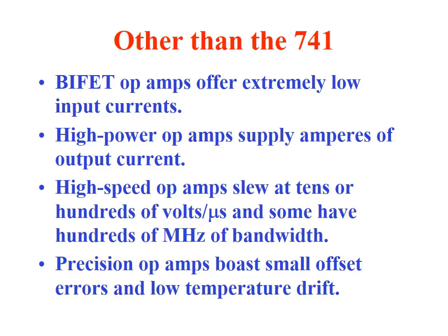And usually, as I said, for some operational amplifiers the unity frequency is 100 megahertz. The precision op amp boasts small offset error and low temperature drift. So that's a better operational amplifier. But why don't we use these operational amplifiers a lot? We mainly use the 741. The main reason is this one is very easy to use, and the second reason is the price. This one is very cheap.